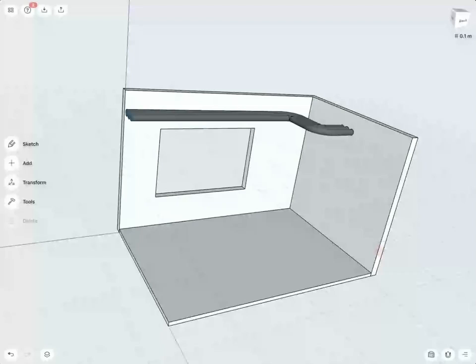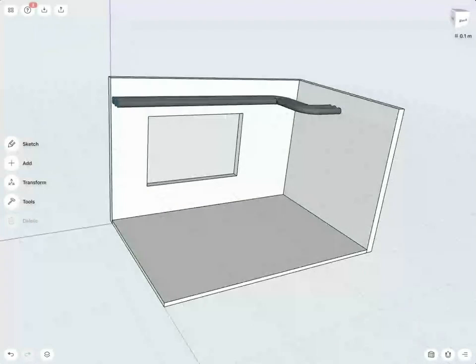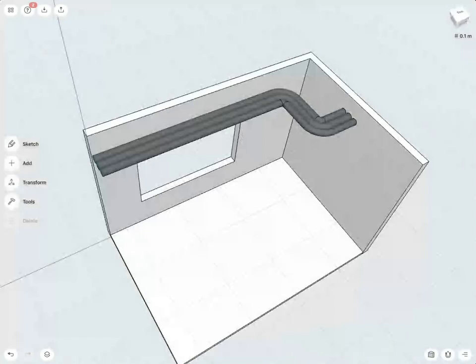Okay, so this was, for example, a quick exercise into when you have to create a visualization where water pipes or heating pipes or something would be inside an architectural space by utilizing the construction plane and then creating sketches and then the sweep command to create your pipes.